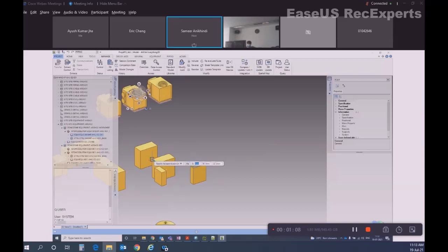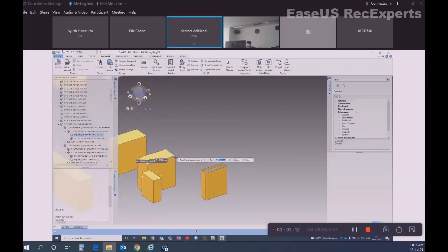So let me select this, and relative to this, it automatically switches back to Cartesian system. So the spherical and cylindrical mode can only be brought on demand. Whenever you need it, you have to use the tilt key. Otherwise, it will switch back to the Cartesian form.